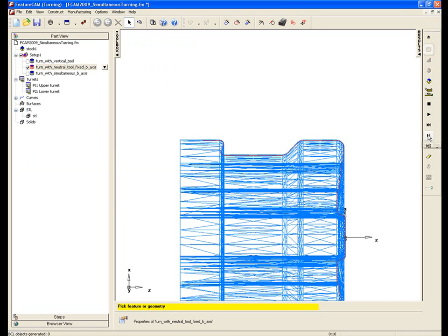So now we've got the right angle to approach inside that region, but now the trailing edge of that tool, or the front edge of that tool, depending on your direction, is gouging into the part at this edge. So this is giving us access to the majority of the job, so now we can machine this undercut region here, but we're still faced with the issue on this section. So it appears that even though we're trying to utilize tool geometry to fit into these regions, we're going to be better off trying to somehow move the B-axis during that process.